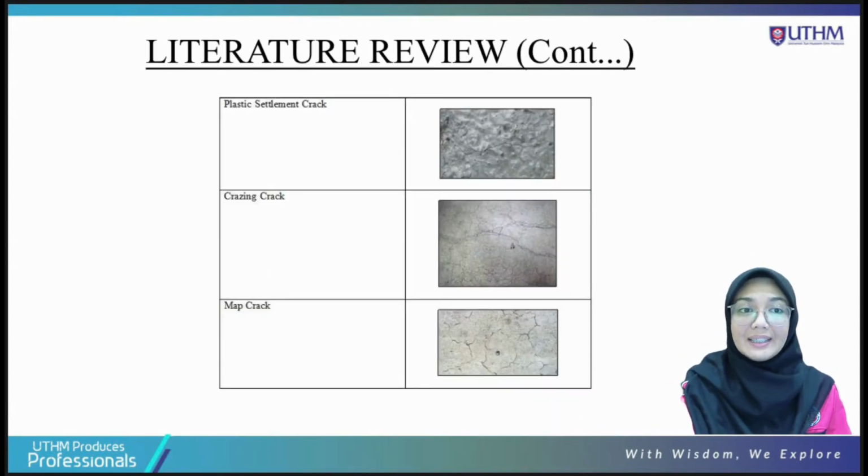For the plastic settlement crack, cracking will develop if there is a lot of bleeding and constraint during construction. However, if the concrete mixture is workable, the concrete will be solid and water will only bleed from the top.